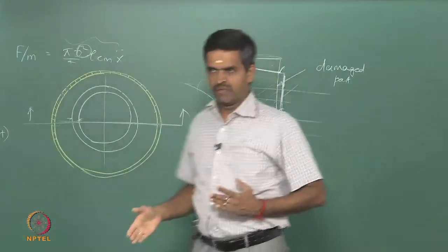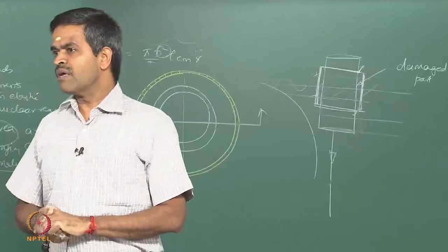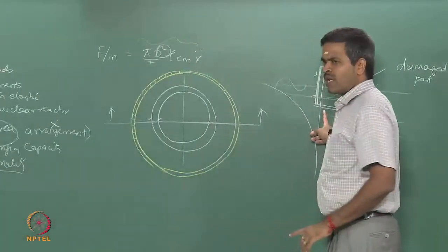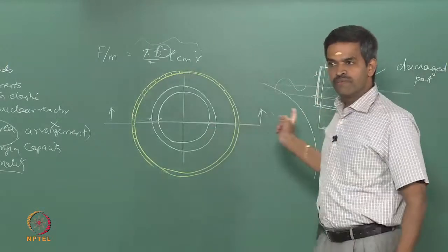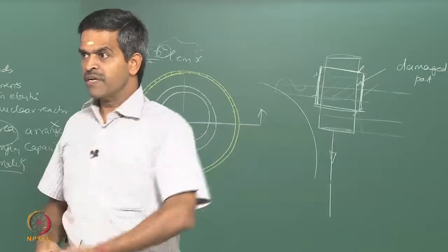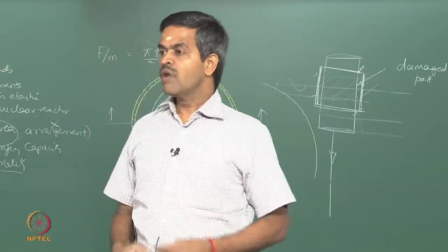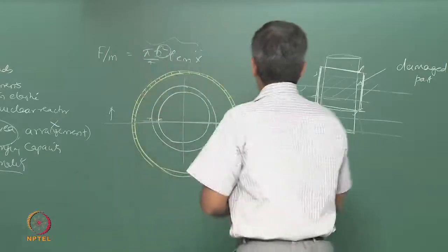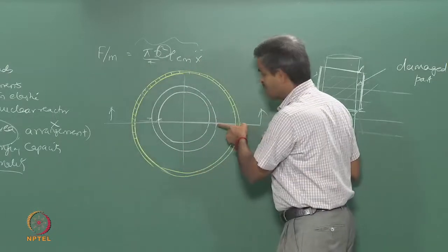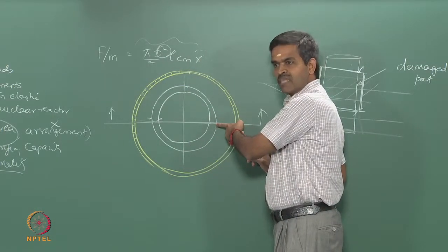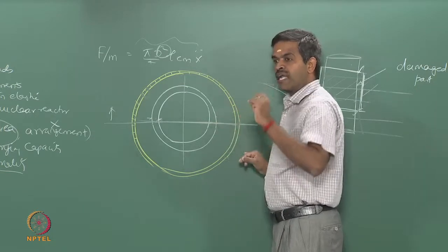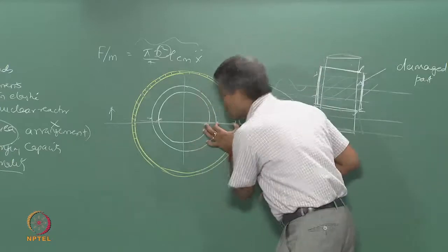for different parameters. Now, it is very interesting that I do not want to know only the force reduction at section 1, but I want to know what is happening within the annular spacing, because I want to categorically show whether it is really decreasing, or increasing and decreasing. Now the question comes, very foolishly, can I narrow down this annular spacing? For example, can I put the cylinder touching this? Because that should also be answered. To answer this, I must know the characterization of the water particle velocity variation within the spacing.